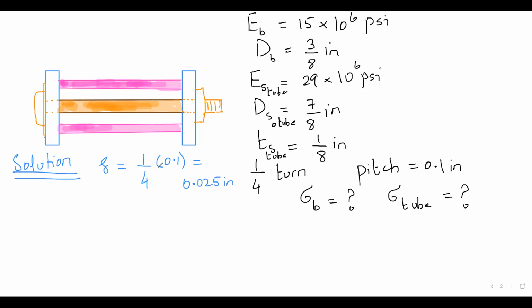And that's it, now you can solve the question. If you read the question, knowing that the bolt is single threaded with a 0.1 inch pitch, this means if you turn it one complete time, it will travel 0.1 inches.